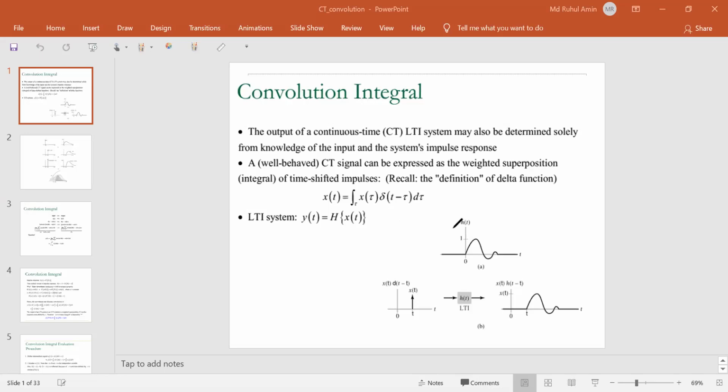If this coincides with correlation, then you can find some relationship between the convolution integral and the correlation integral. But in terms of system responses, when we know our system impulse response, we will use convolution to find the zero state response of our system.